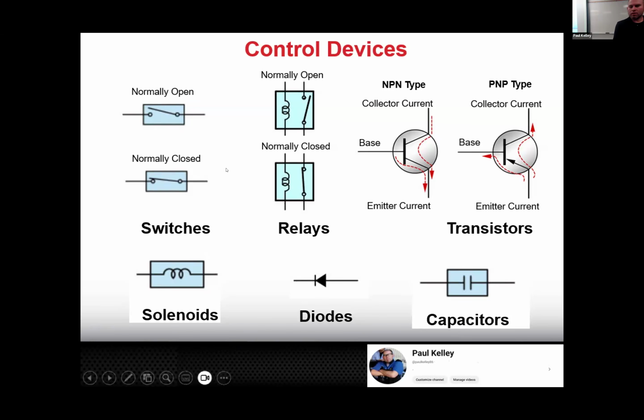And then if you look at relays, I feel like that is the next logical thing to cover. If you look at these relays, that's a normally open relay. So look at the right side of that relay. That one is open. We would test this switch of this relay the same. There should be no continuity until we close it, at which point we should have good continuity.